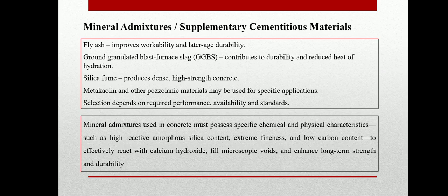Silica fume produces very dense, high strength concrete often used in high performance applications. And materials like metakaolin and other pozzolanic materials are used for more specific and specialized applications.